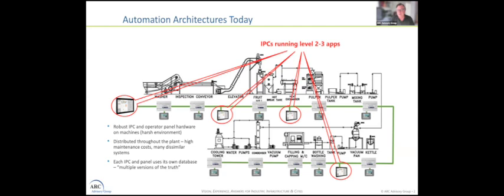So the end user here, the juice maker, when he plans his new line, he buys the best of breed equipment from companies in Germany, companies in Italy, and they build their equipment. They put their PLC on it at the factory to test it, and then they send it on a truck, and it gets reassembled at the customer site, and everything is then connected and integrated. So this is the classic architecture that we've been used to for many years.